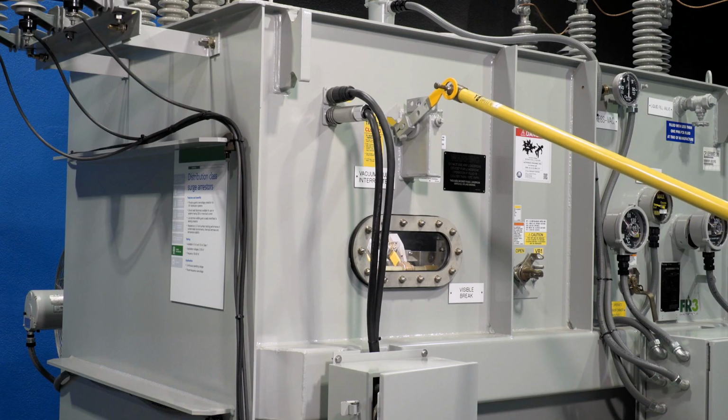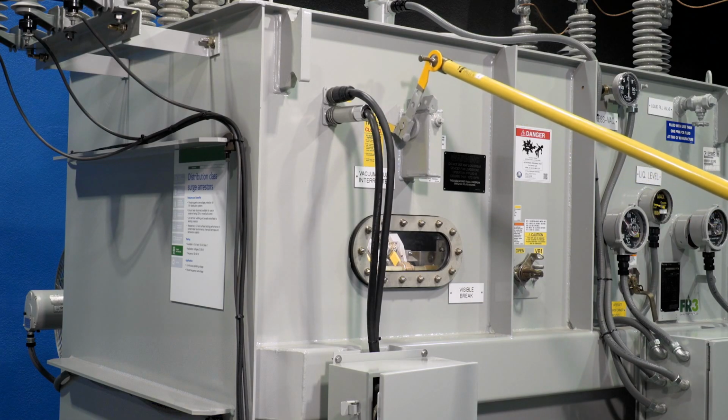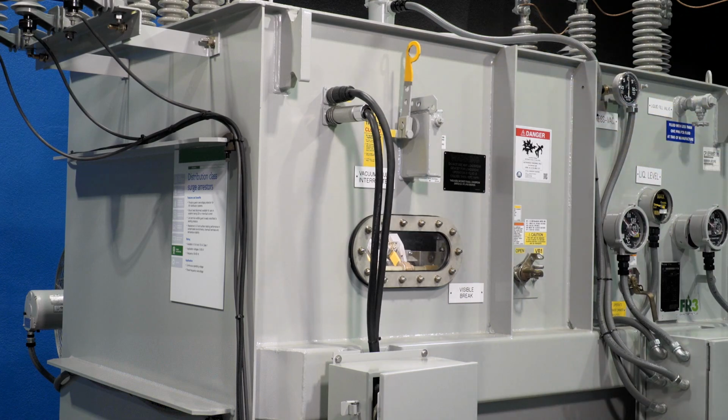The VFI mechanism is opened by pulling down the operation handle into the open position. The VFI mechanism is closed by briskly pushing up the handle into the closed position. If the VFI mechanism has tripped as a result of a fault or overload condition, the mechanism must be reset before it can be closed.